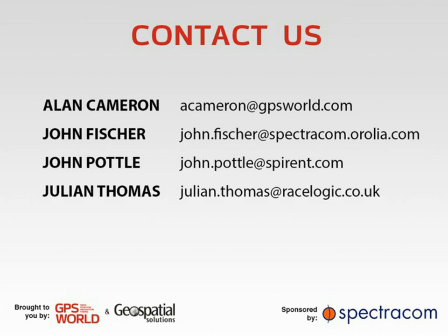Great, thank you, Alan. Yes, so the challenge in multi-constellation receivers, and again, this is the receiver designers who have these challenges, is the fact that each separate GNSS system has a different time base, and they do a lot of things to coordinate and control them so that they match up, or they're at least known differences, but they are different. And so a big challenge for the multi-constellation receiver maker is to deal with those time sync differences and how that might affect accuracy.